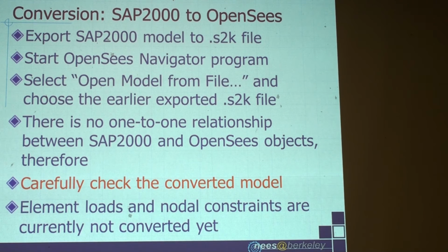So if you use that conversion capability, like I highlighted here in red, carefully check the model after you convert it, because there is obviously no one-to-one relationship between SAP 2000 and OpenSees.